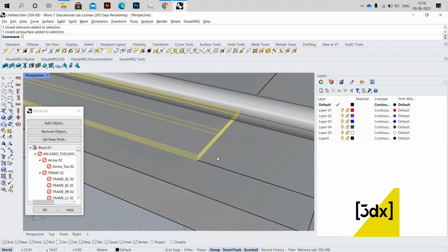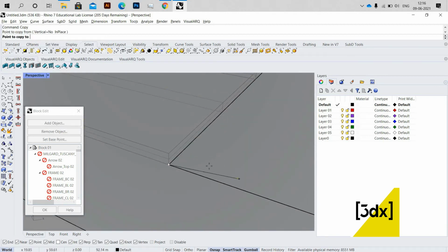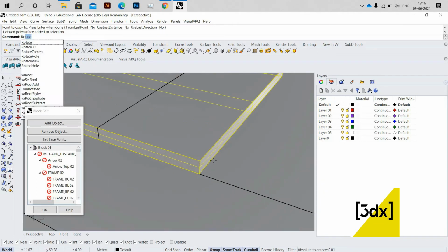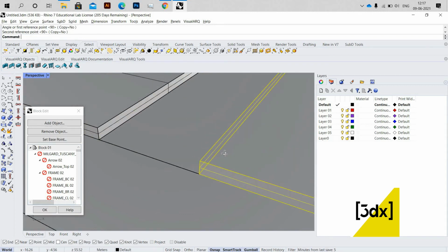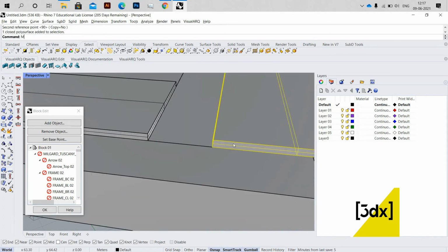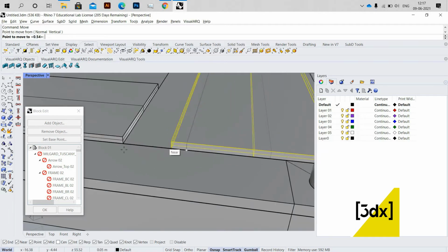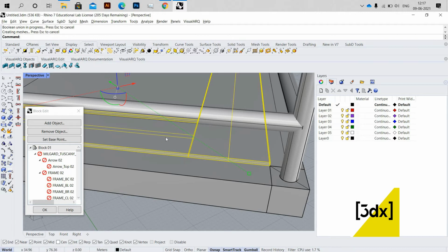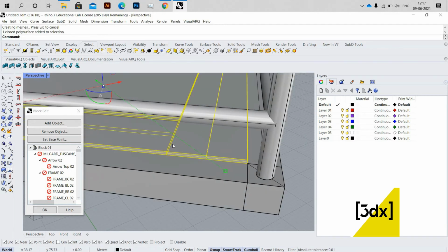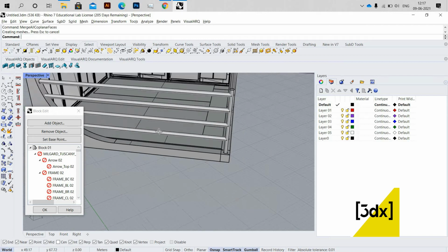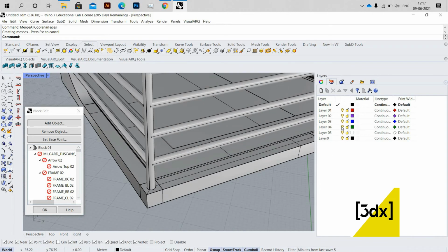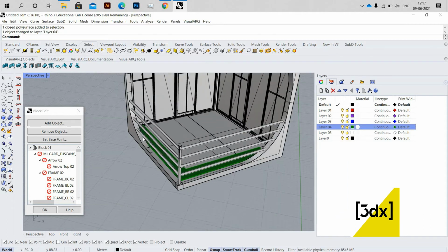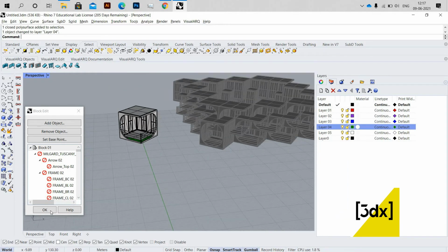So I need to do this for the same like this. You can copy like this, and you can do all. You can use offset surface, or you can use extrude surface. There are many options right now which will do similar steps, but you should get organized about where you should use this, and it's up to you. I use it like this sometimes. My friend used to do extrude surface, and I'm just joining these two by using boolean union, and I'm giving merge coplanar to hide the line and make it perfectly smooth, butter smooth.